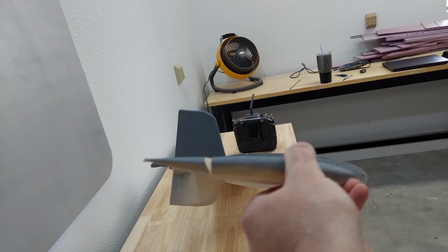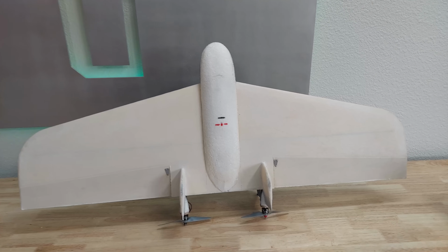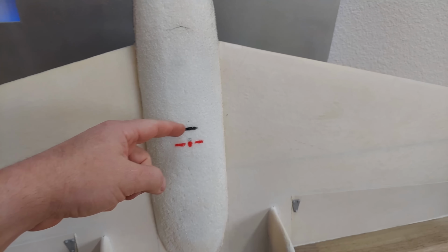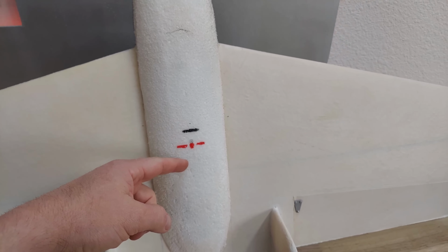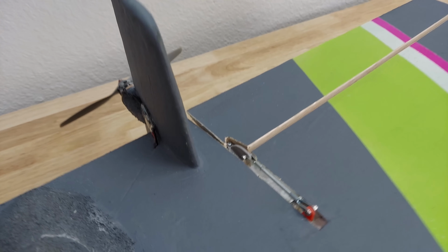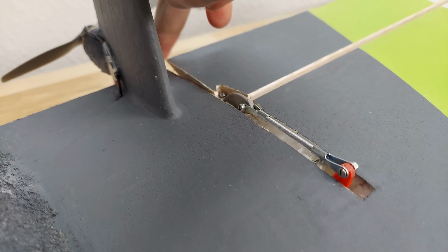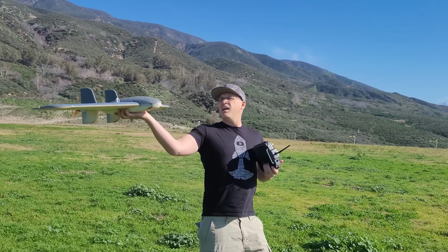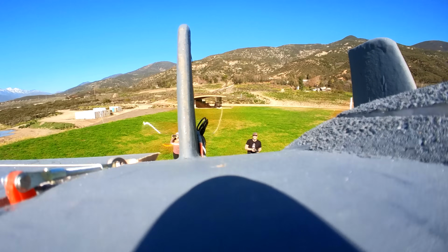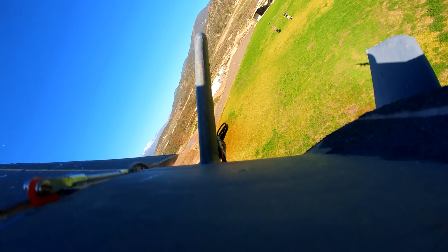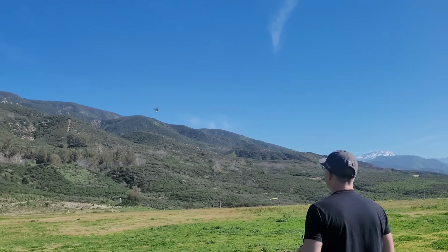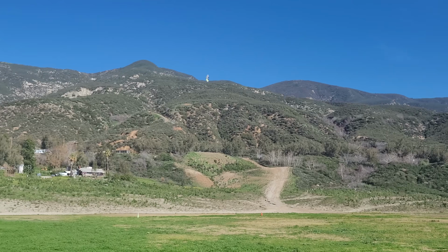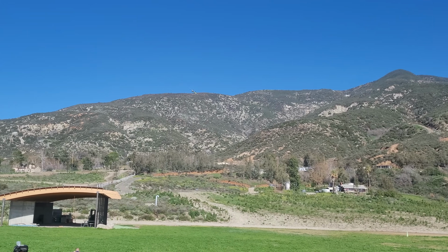For the first flight, I set this up like a typical aircraft. The black line represents the center of gravity, and it is in front of the neutral point, which is the red dot. To counteract the weight being centered in front of the neutral point, we raise the elevons to pull the nose back up. This is a stable system. That is without stabilization. That is without the computer in the loop.